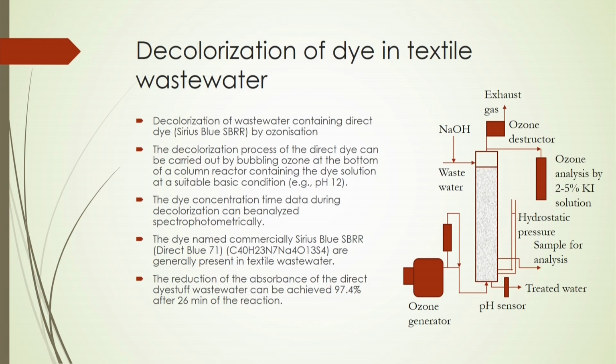Now, in this case if a colored dye is being processed by these ozone bubbles, maybe microbubble systems, or even sometimes conventional bubbling systems, you will see after a certain time whatever dye compounds are there will be degraded and converted to colorless. Then you can say that the advanced oxidation by ozone through these bubbling systems is effective for this particular process, and it will happen at a particular pH value, whether it is acid or basic medium. That is important to know.